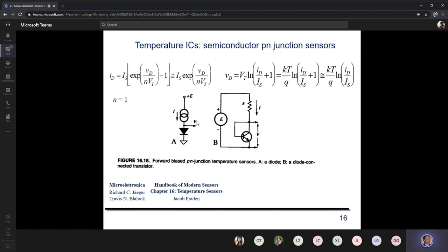You remember that if you consider the series of a voltage generator and a resistance, and if you consider both large, then these two elements together are roughly equivalent to a current generator. Okay? It is an easy calculation. So essentially, circuit B is conceptually the same as circuit A.